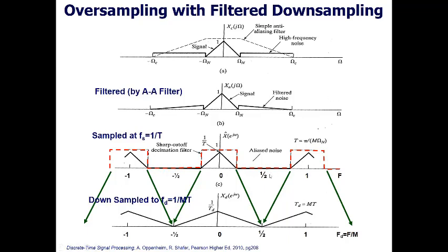And this extra digital filtering both prevents aliasing from getting through from the original signal and any aliasing that might happen in the downsampling process. And so we end up with a clean anti-aliased signal at a sampling rate that the rest of our hardware can deal with.